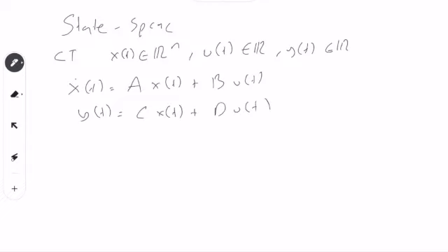Okay, and using this representation, we can analyze stability. We can analyze its robustness by converting to the transfer function, looking at phase and gain margin, and we can design state feedback controllers and Luenberger observers. Okay, so the good thing about state representation is it's easier to extend it to time varying and nonlinear systems, which is similar, and I think it's even easier compared to the differential equations.